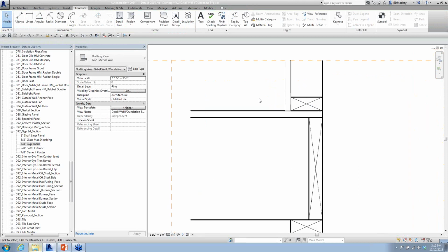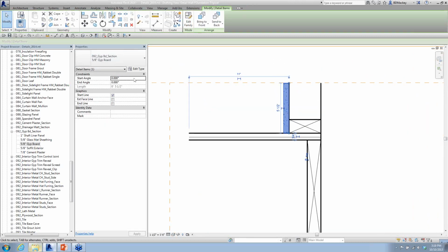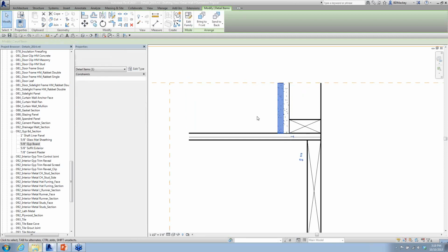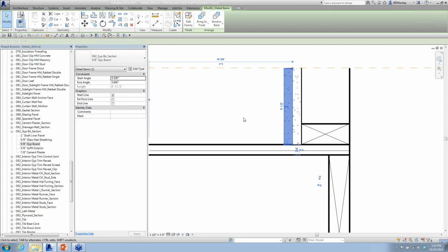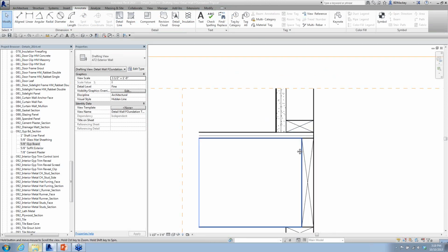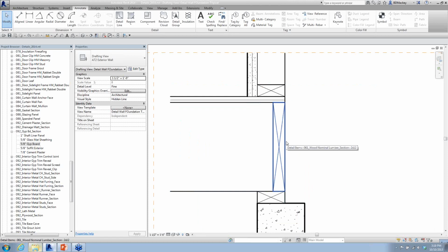So some of the other things that I like to build in is I know that if I had like 2 layers of gypsum board when I was working on this, that on that outside layer of gypsum, what I might want to be doing is seeing that as a fatter line when we bring this into it. So all of my families also, I include what's called the exterior face line. And what that exterior face line is going to do is be pre-built inside of there the fact that I can make this object bold or not bold when I start going into it. So as I place brick down, as I start placing the gypsum sheathing down, all of those different things inside of there are going to allow me to come through and start really showing here's a fat line to give us that detailed look that most of the architects like to do.